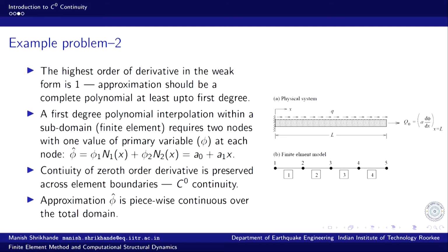So, it is a very structured system of information that makes it very convenient for computer programming and automatic computation. So, this finite element model eventually leads to what we call the connectivity array or mesh, the finite element mesh. That data, the connectivity array or the mesh data, involves specification of which element is defined by which nodes, and nodes are defined by their coordinates.